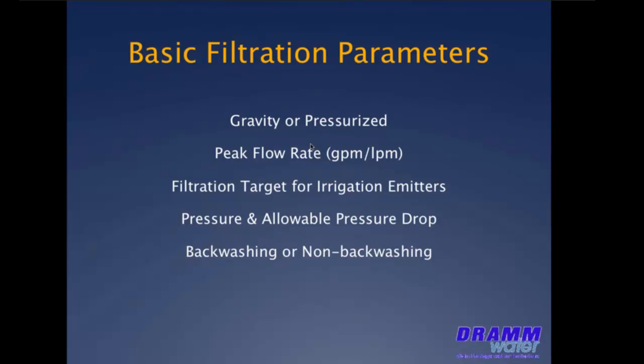And then the question of backwashing or non-backwashing. Again, this is becoming more important as more states and municipalities adopt restrictions on backwash from filters. In the state of California, for example, the state says no backwashing from filters is allowed. It's not necessarily policed, so there are a lot of growers that are still backwashing filters, but it's important now to address the question in the design and know what the answer is before you select a filter system. You don't want to spend a lot of money on a filtration system that's backwashing only to find out that you can't backwash a year from now.